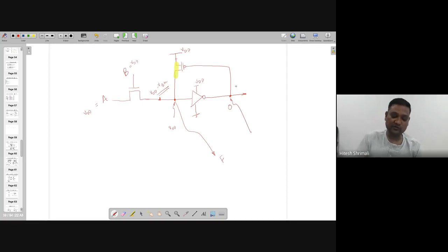You don't need to look at this output. However, this output was also fine, but this particular thing is going to be executed when this is VDD minus VTN and the output is 0. In case of output as VDD, this transistor is again off, and there is no role for this transistor. Okay, so we need to understand that if this is 0, the output is VDD and this transistor is off, then this loop will not be there. This is known as the bleeder transistor.